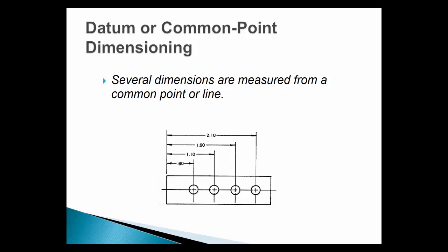Baseline dimension is a better solution. In this example, the tolerance amount is applied properly to each hole location as intended.